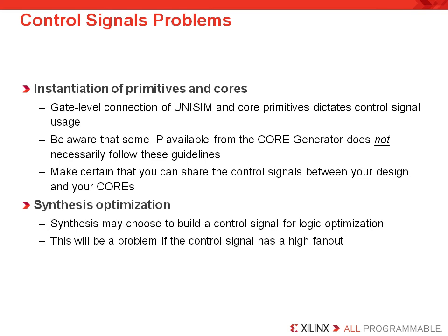It is important that you understand that the FPGA architecture also dictates what types of control signals can be used. For example, a block RAM has a synchronous output register. If you try to infer an asynchronous output, your synthesis tool will not infer that output register. This can affect your device utilization and output performance of that block RAM. Your synthesis tool can also infer a high fan-out control signal, so be sure to evaluate what you're getting with your synthesis tool schematic viewer.